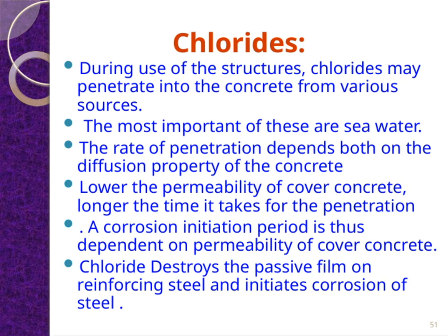Chlorides pose a serious threat because they destroy the passive film that normally protects the reinforcing steel. Once this film is compromised, it can trigger the onset of steel corrosion, which can significantly weaken the structural integrity over time. So, to summarize, controlling the permeability of cover concrete is crucial in delaying chloride penetration, and consequently, extending the lifespan of reinforced concrete structures exposed to chloride-rich environments like seawater.